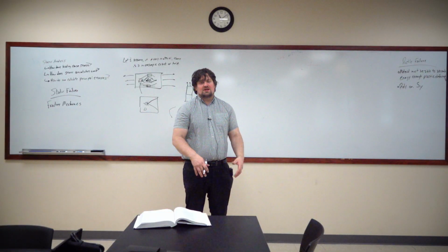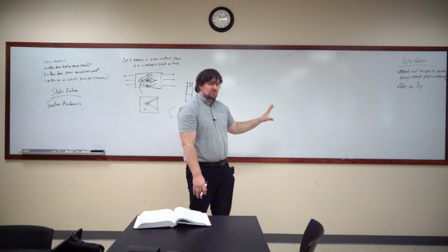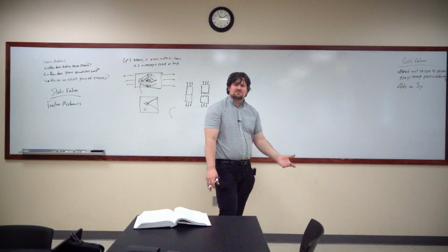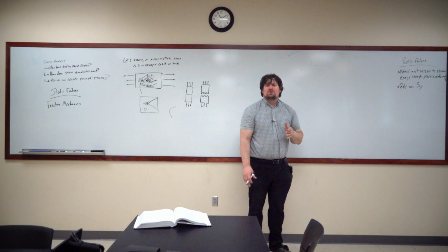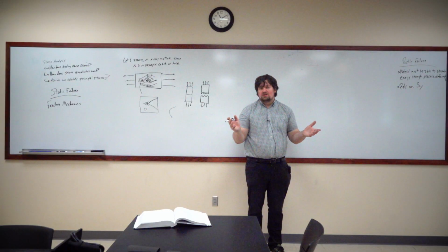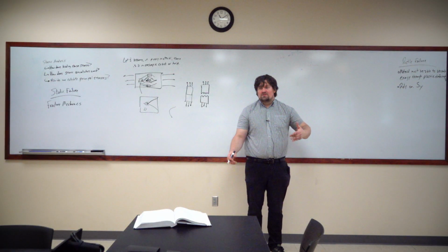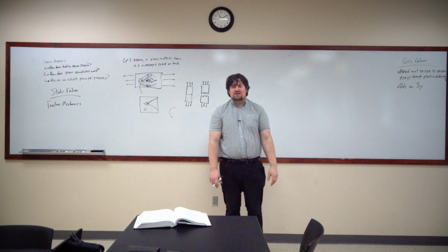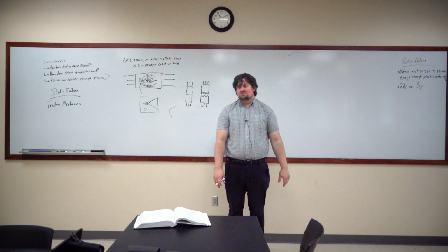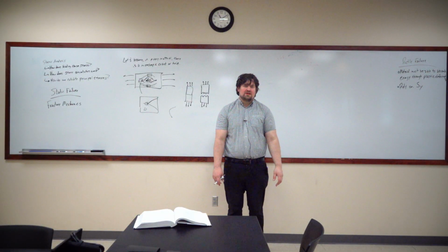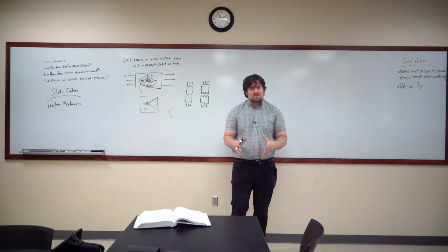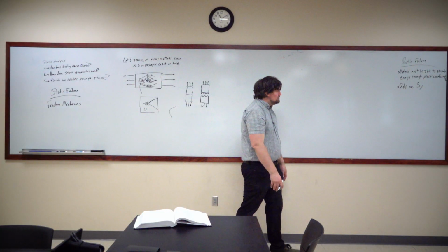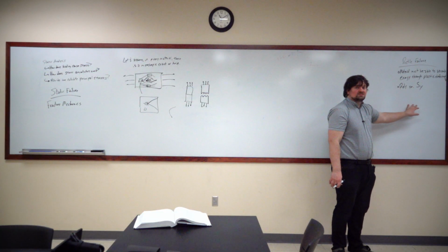When we're talking about ultimate strength or ultimate rupture, we are talking about brittle failure. In ductile failure, all of the mechanisms we have in the book that we're going to be discussing in this class have to do with the fact that we do not want plastic deformation to occur. If you can imagine the piston in your engine suddenly expanding, it's going to cause your engine to seize, and a lot of bad things happen. You don't want that plastic deformation of the piston head because it disrupts the entire flow of your system. So here we're going to rely on Sy.